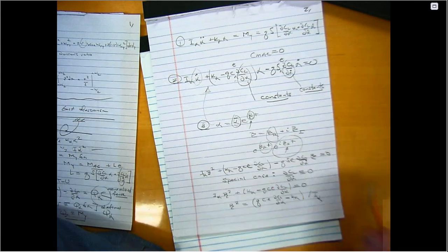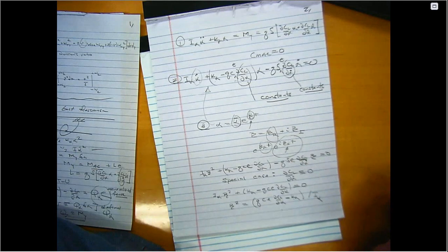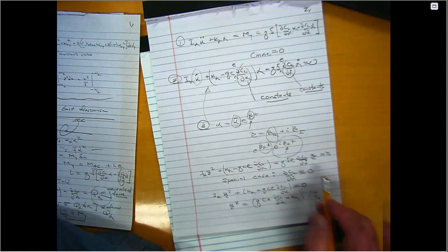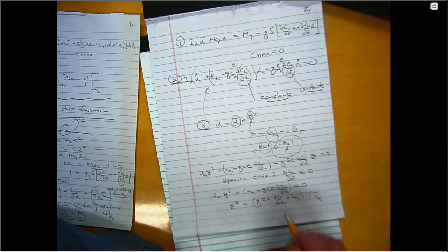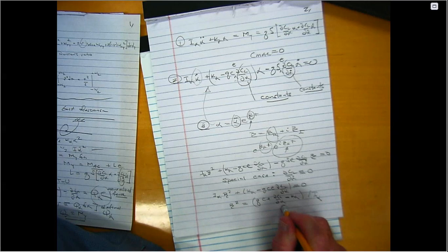So, do I call that a stable system or an unstable system? Well, it depends. That's a good answer. What does it depend on? When we put the beta term back in, we'll see if there's a little margin. But strictly speaking, this is neutrally stable. What does that mean? It means we can't make up our mind. It doesn't decay, doesn't grow. It's not going to become unbounded. So it's neutrally stable. That's what people usually say.